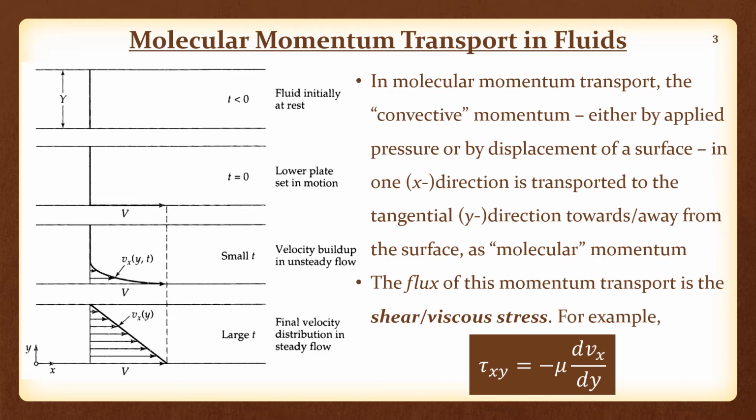Basically the molecular mechanism of transport by way of contact, by way of the sliding motion between two fluid particles, which, if you were to look at what happens at the molecular level, is breaking and reforming of the secondary bonds, right?